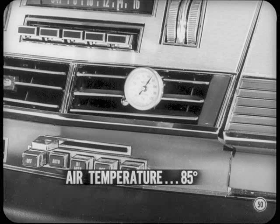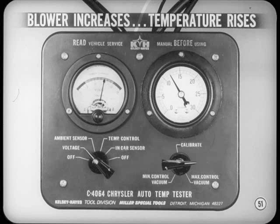Right, Jack. And at the transition point, the output air temperature should be at about 85 degrees, give or take 10 degrees. Then, as soon as the change is made, the blower starts to speed up, and the temperature continues to increase. As you continue moving the dial toward maximum vacuum, the blower will make 2 more increases in speed, and the output temperature will continue to rise. At 12 inches vacuum, the blower will be on M3, and the temperature will be about 140 degrees.